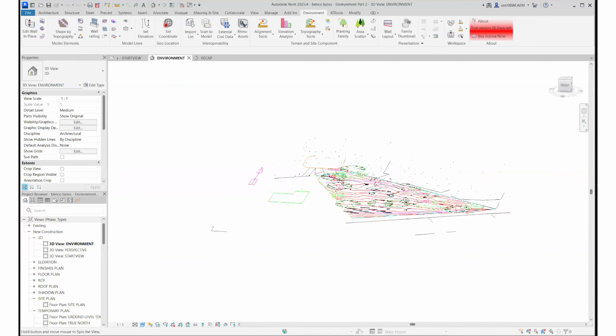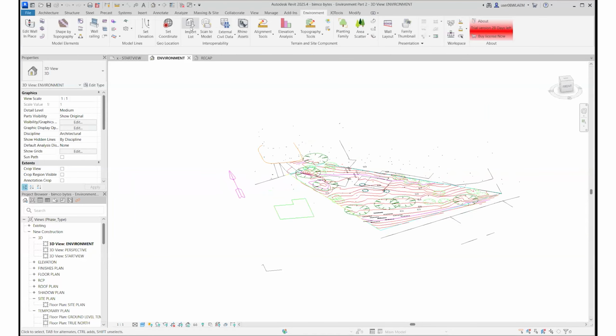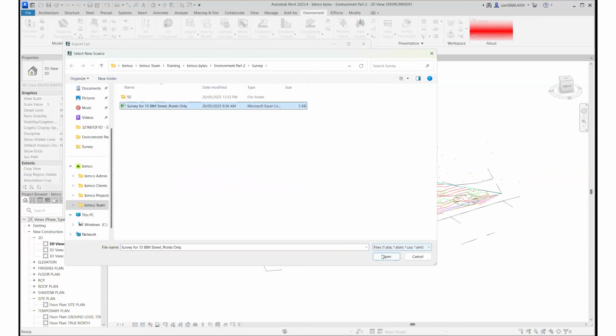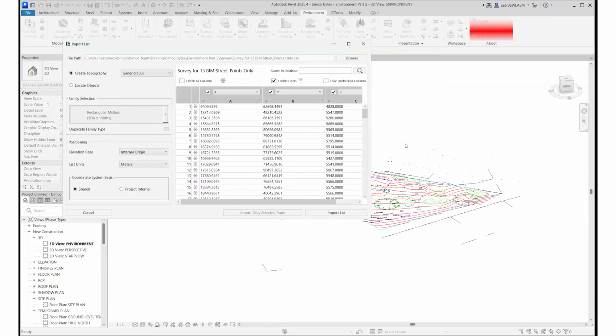The first thing we'll do is look at this button called Import List. A bit of background: this button obtains a CSV file. As you can see in the 3D CAD file, a data extraction command was done to produce a spreadsheet file based on X, Y, and Z elements, which you can already see over here.